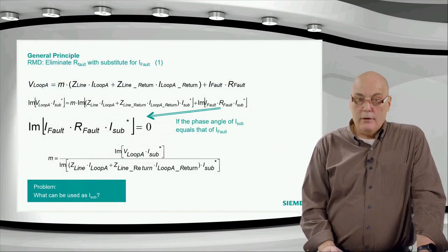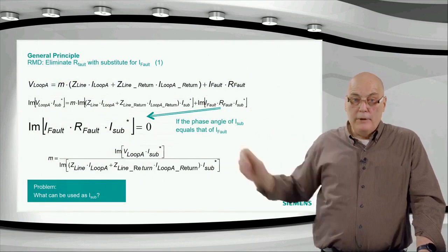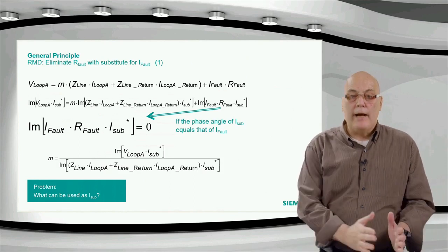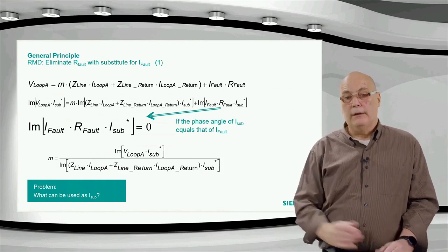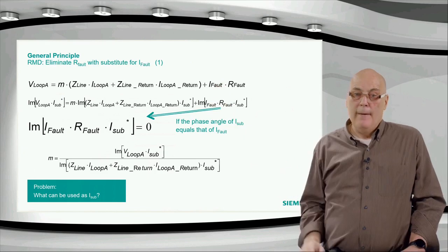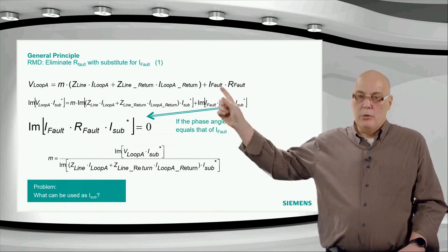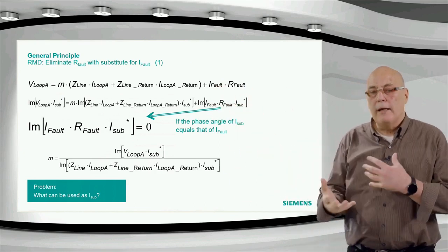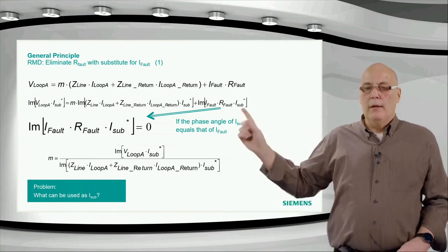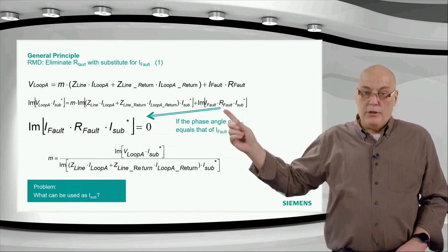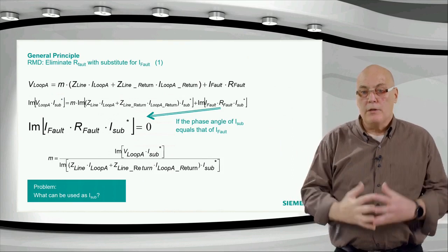Alternative to that, we have a distance protection with RMD. You can see the top in the heading. This is the reactance method distance protection. It starts with the same equation here, but it is not simply going to assume that this is not existent. It's going to use a mathematical method to compensate for this, to extract it, or so-called load compensation.